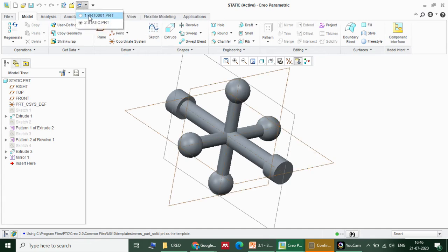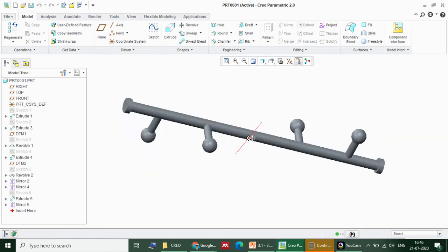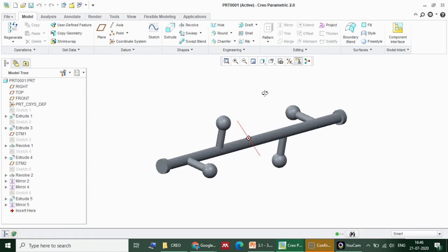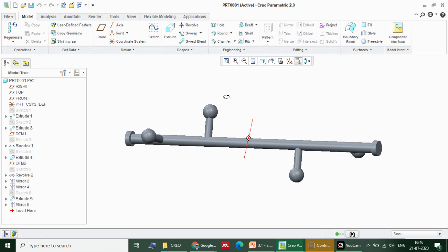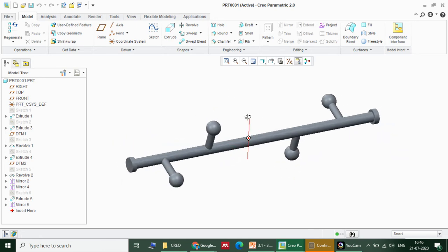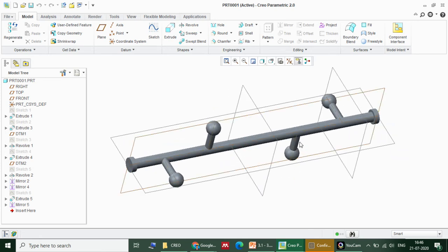So in this case, we go for creating force polygons and couple polygons, and then we finally end up with the resultant force. We find out where the resultant force is located, and we put an opposing mass. We create an opposing force to that resultant, so that the resultant force is cancelled out. That is the basic idea of balancing.